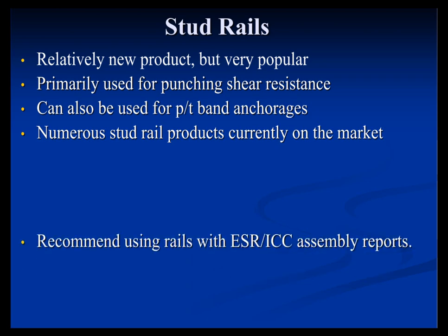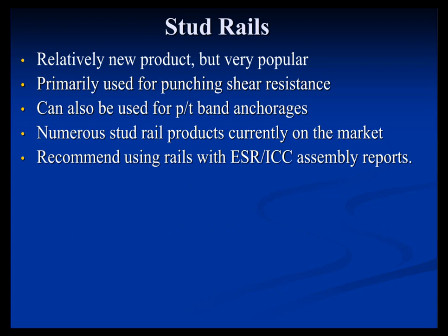And the reason I bring that up is because when we first started using stud rails on flat plates instead of caps, and typically in my experience, and this is a Brian thing, stud rails work better when it's single level loading, meaning a garage, an apartment, a hotel, an office building, whatever it is, but it's a single level. Now, if you have a podium type structure or something where you are substantially increasing the slab thickness based upon load, not based upon span, then I typically think that stud rails aren't maybe the best choice, that you should go with caps.